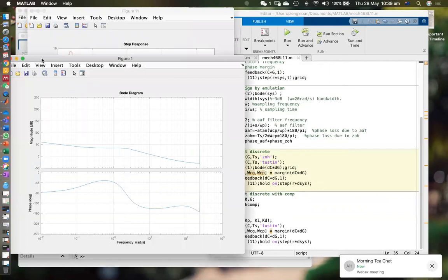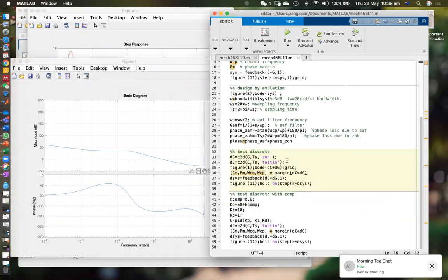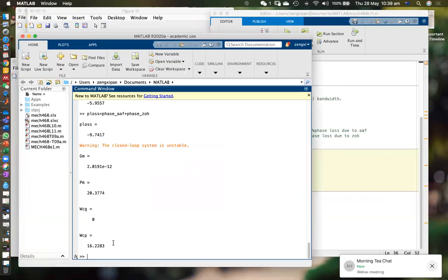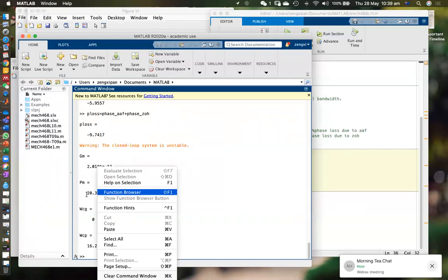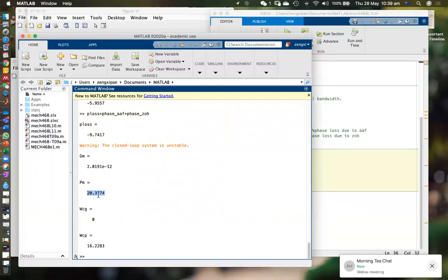And if we look at the phase margin, because I print this in the box, it's become 16 degrees, right? There's no magic, right? Because we started with 26 and we estimated going to lose 10 and we actually lost 10. No, sorry. We lost not 26, 20. Sorry, I got it wrong. Phase margin is 20. We start from 26. We lost 6 over here. Our estimation is going to lose 10. So you can see there's a slight difference here.